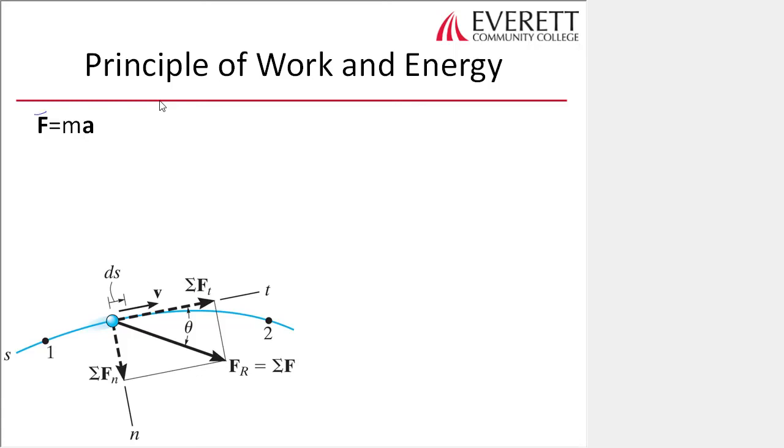And we start off with Newton's second law, no shocker there. And we keep in mind that that is actually the force in the tangential direction equals mass times acceleration in the tangential direction. And we also know a_t ds equals v dv. We recognize that this component of acceleration, the tangential component, is the one that's in that kinematic equation. We talked about that in kinematics. That's only the tangential component. The normal component is due to change in direction, whereas this is due to a force.